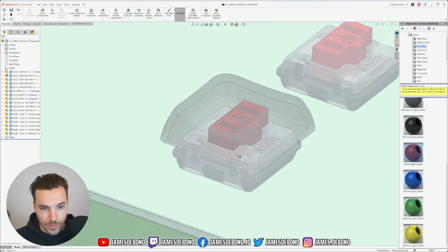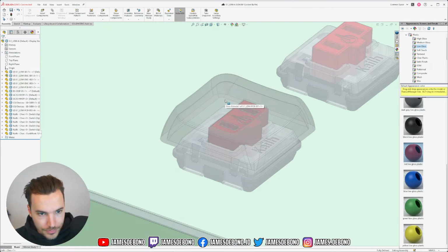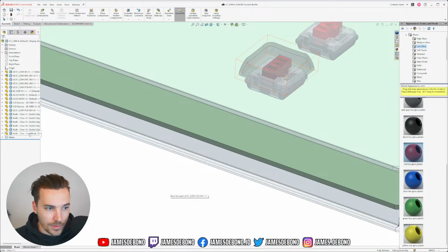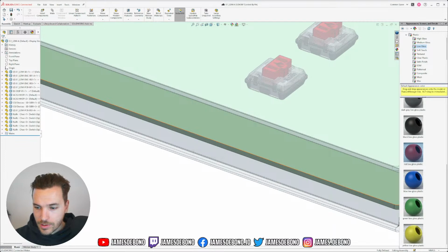so the light is lighting up the whole key. But we'll paint black, probably some kind of black paint or black coating over it, and then maybe laser etch the label of the button. So we laser etch play into the surface, which means a laser will cut through the black coating on the top, and it'll leave behind the transparent material underneath it, and the light will shine through that, so that you'll see the text illuminated. That's going to be pretty custom, so I think in the end we have to have custom switches. So that's what I'm going to do. I'm going to make a custom switch.